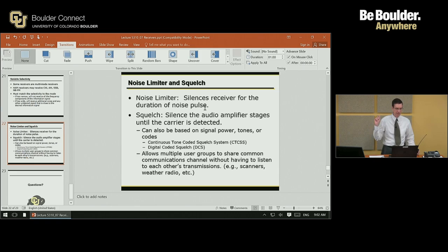So when it hears the tone, it says, "Okay, I will open up." And that tone's at something like 100 hertz, fairly low, so that when you're having a conversation, you don't really notice it. So that's what it has on it. And if I talk into this, it will hear that tone, and then it will come back. So let's see if it does that.